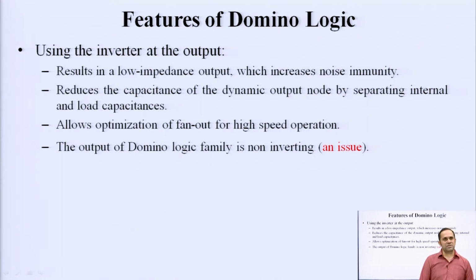It reduces the capacitance of the dynamic output node by separating internal and load capacitances. It allows optimization of fan out for high speed operation. And the output of a domino logic family is non inverting. Now, this is a sort of an issue